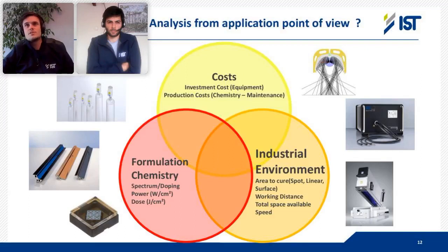Depending on the power and the size of the curing needed, some technology won't really make sense because the cost difference would be too high. For example, when you want to cure a glue spot, it is way more economic and efficient to use a small UV LED component, so the UV LED technology, than a big mercury lamp.